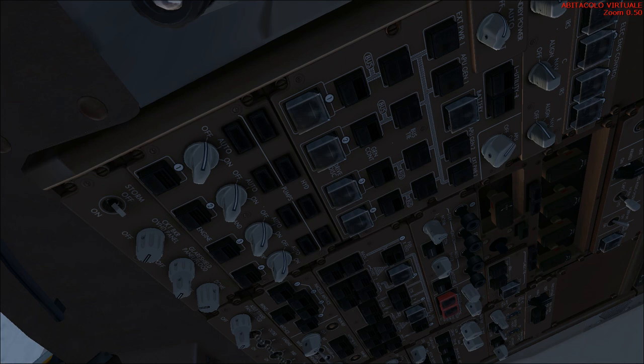The batteries actually power up a part of the DC circuit, the vital or hot buses of the aircraft. The DC hot buses, because it's a DC source, are directly connected to the battery. They can be disconnected from the battery. So every time the battery is powered up, you will have power to these vital or hot buses. You can also convert the DC power of the battery into AC power using inverters.